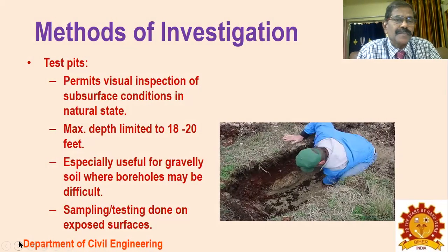Methods of investigation. Test pits. It permits the visual inspection of subsurface condition in the natural state. Maximum depth is limited to 18 to 20 feet, especially usually for gravelly soil where the boreholes may be difficult. Sampling and testing are done on the exposed surface.